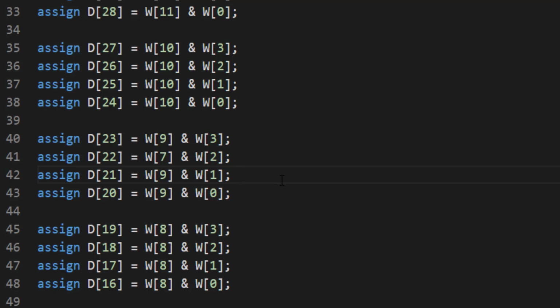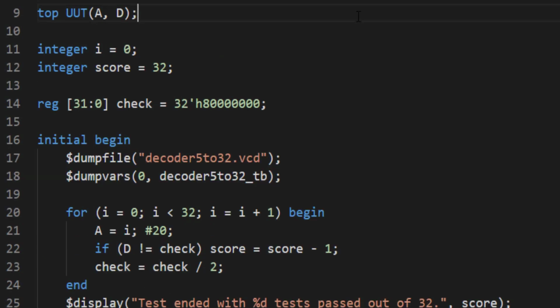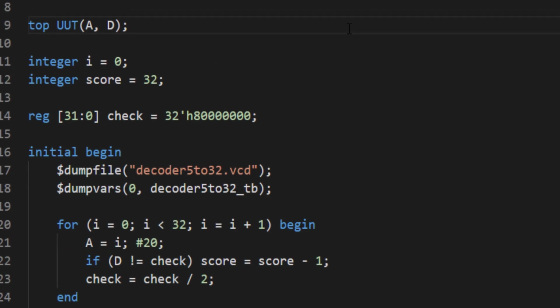In test engineering, we call this the empty socket test, right? A lot of times in the testing class, we have, oh, look, the test works, and then you pull the device out of the socket, and the test still works. We want to actually create a failure, right? We want to create an instance in which our test bench fails, so that we have at least some confidence that our test bench is working correctly.